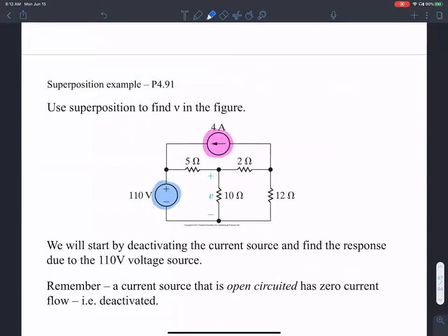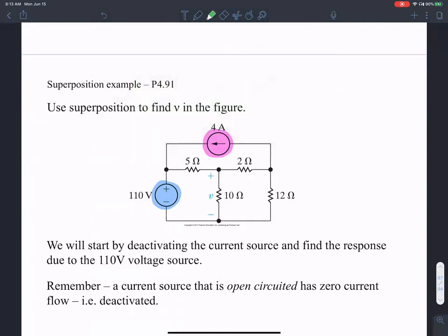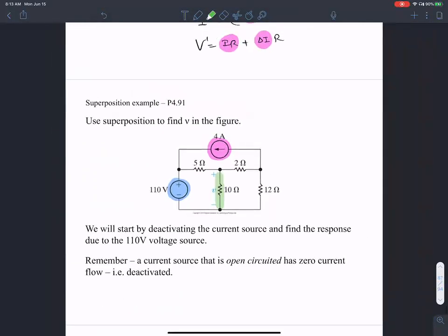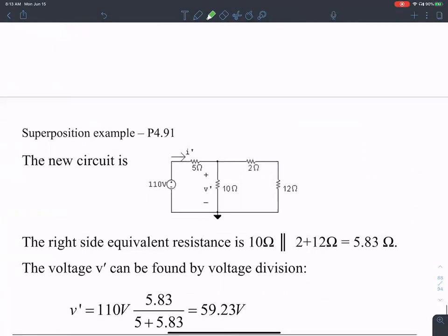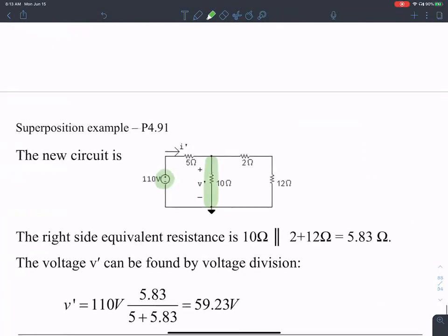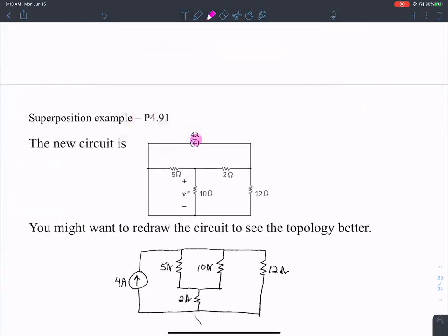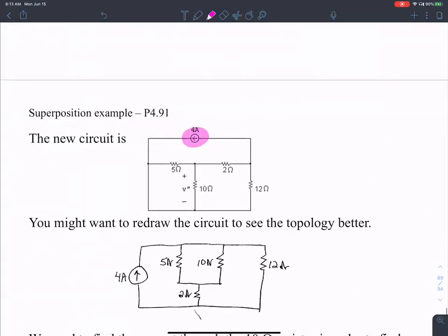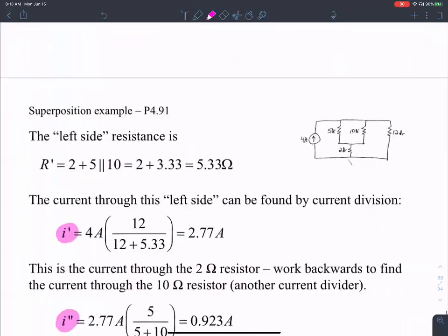When there are two independent sources, and you want to evaluate the effect of that on the circuit, the idea of superposition is that I can independently evaluate the response or the behavior of the circuit to one source and the other source independently, then add them up together. Okay, so for example, I'll show you in this example.